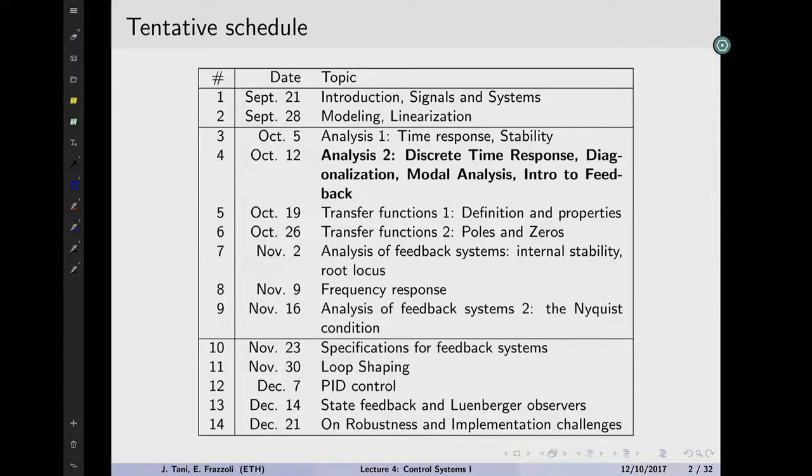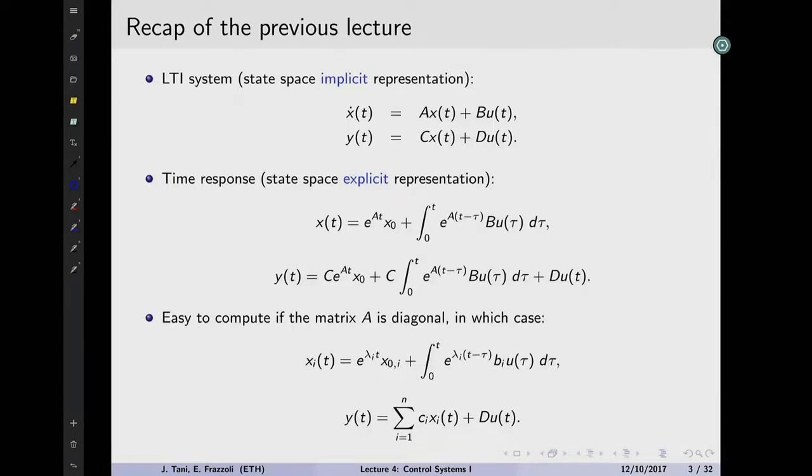So this was interesting. We wrote down these state space representations of linear time invariant systems, which is the x dot equals Ax plus Bu equation coupled with the output equation y equals Cx plus Du. And we recalled that, of course, we've got a u of t as input, we've got our system, and we've got y of t, which is the output, right? So remember, u is the input, y is the output. In this course, we just study single input, single output systems, which are SISO. And this means that the input is just one number, the output is just one number.